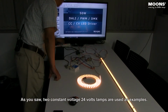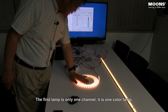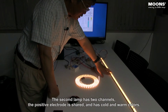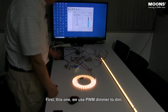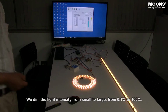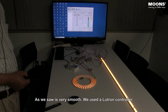As you saw, two constant voltage 24 volts lamps are used as examples. The first lamp is only one channel, it is one color lamp. The second lamp has two channels, the positive electrode is shared, and has cold and warm colors. First, this one, we use PWM dimmer to dim. We dim the light intensity from small to large, from 0.1% to 100%. As we saw, it is very smooth.